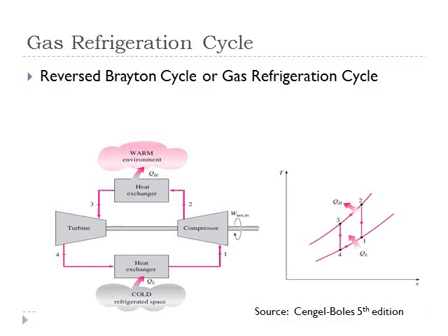From 2 to 3, we have heat exchanger, where heat is being rejected by this heat exchanger, since during the 1 to 2 process the compression work will increase the internal energy of the refrigerant, so its pressure and temperature both will rise, as we can see the same effect in TS diagram.